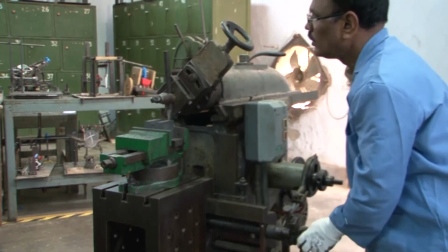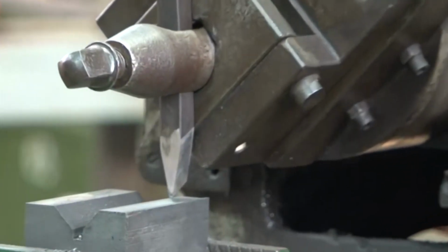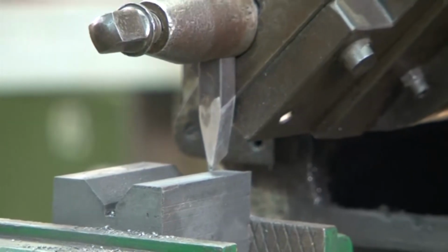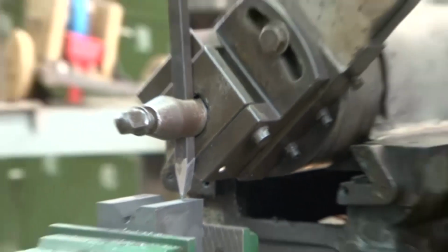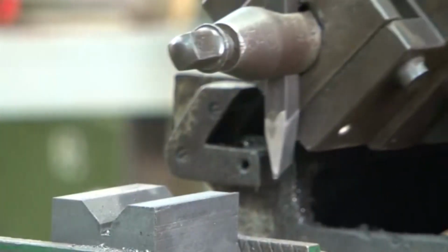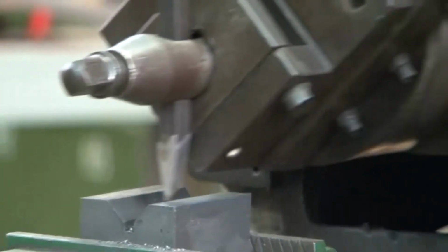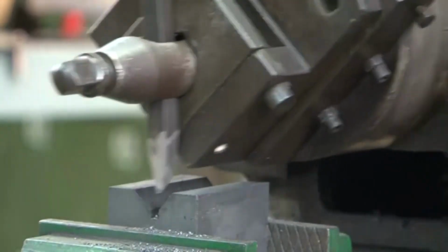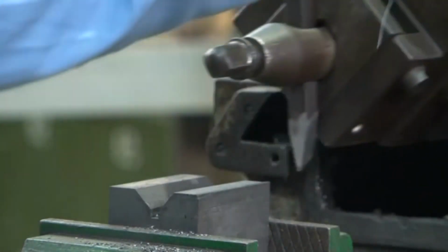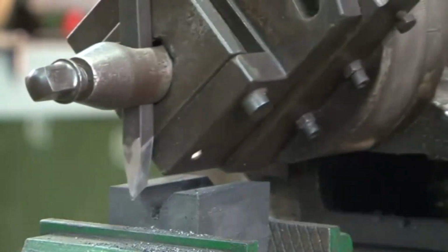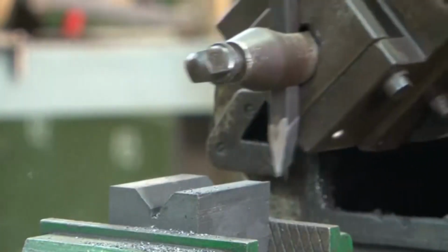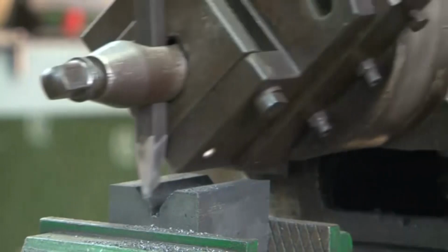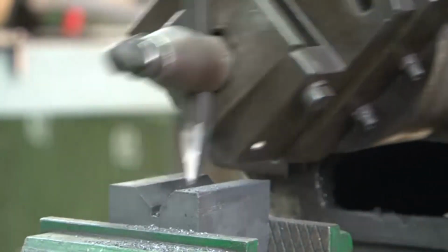Yeah, he is ensuring that the tool is in contact with the workpiece, so that the depth of cut can be given and the surface can be made. Okay, the machine is on now and the depth of cut is given. You can see in the backward movement the tool is being lifted up, because the depth of cut given is little more than in the previous case when the flat surface was produced.